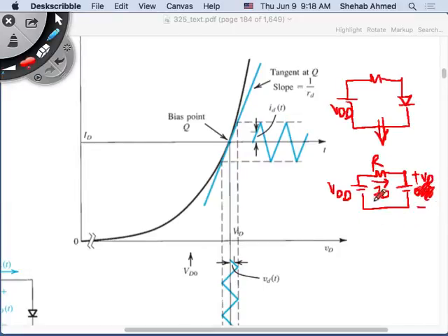In general, we had this power supply, VDD, and a voltage across the diode, VD, which we modeled as this battery, and we had this resistor here. We found the current flowing using two equations and two unknowns. You don't know the current, and you don't know the voltage across this device. So we found another equation in the same two unknowns using the diode exponential equation, which had VD and ID in it as well, and we applied either iteration or graphical methods to find the operating point. So we found this operating point.